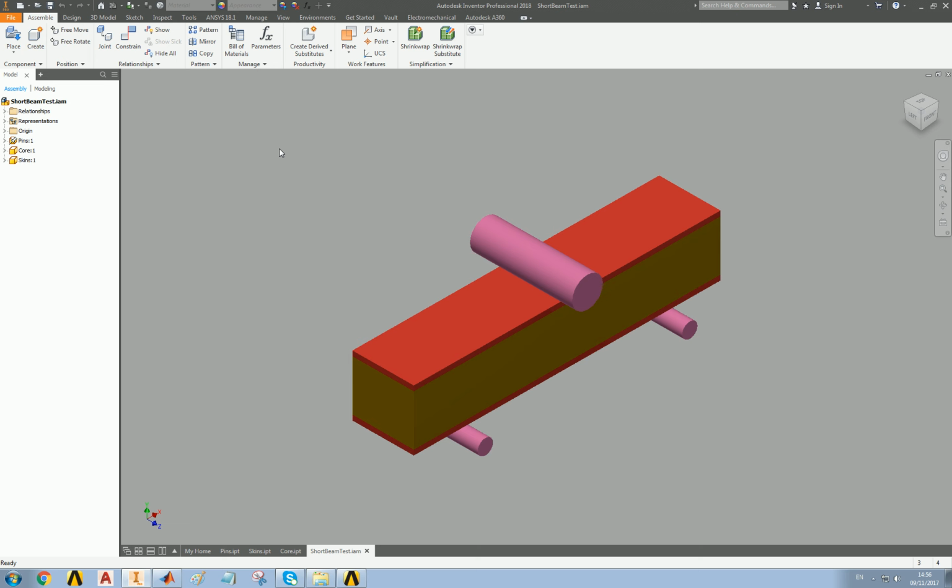There are two planes of symmetry here. We have this plane of symmetry, which means that that solution will be the same as that solution, and we have the xy plane again, so that backwards and back and front will have the same solution. So technically we only need to solve 1/4 of this, and then we can extrapolate to the other parts of the other quarters of the problem. So how do we do that? Let's go.